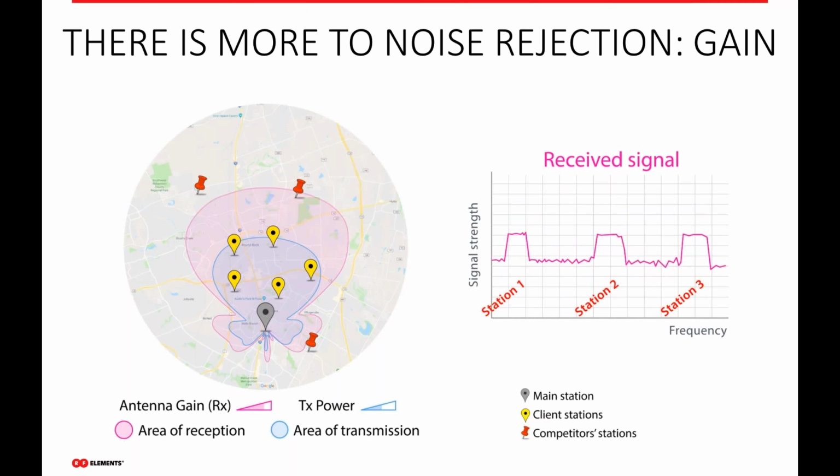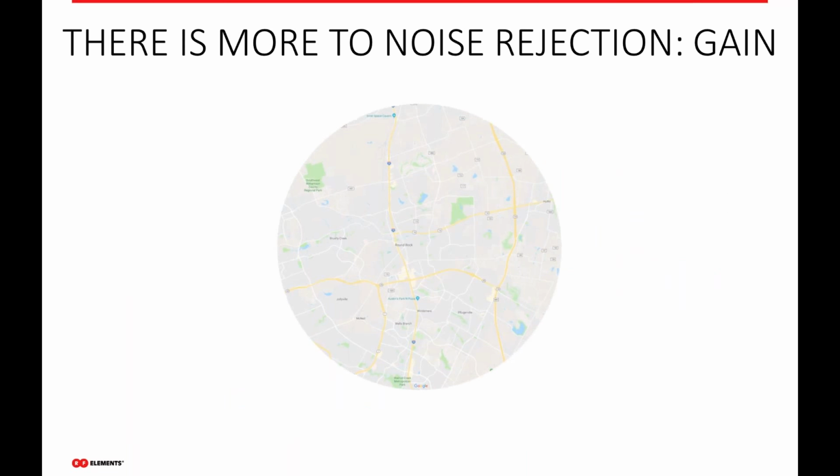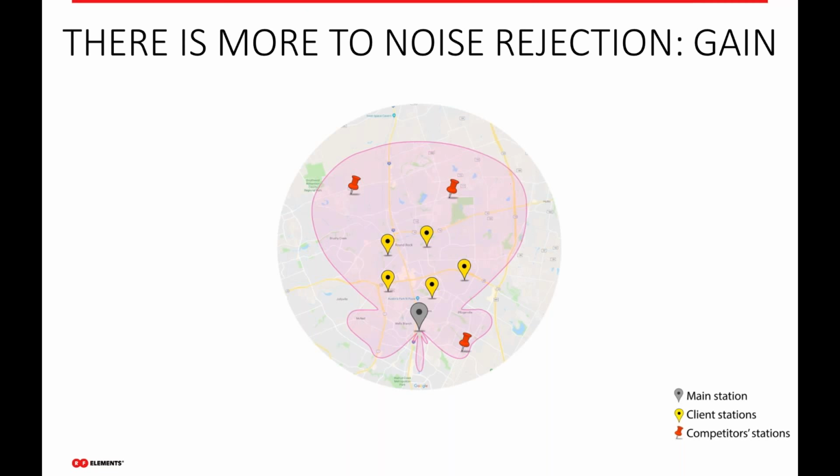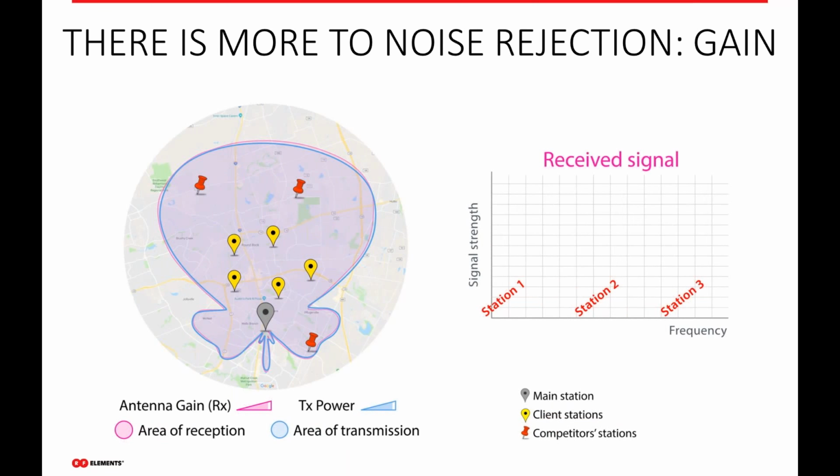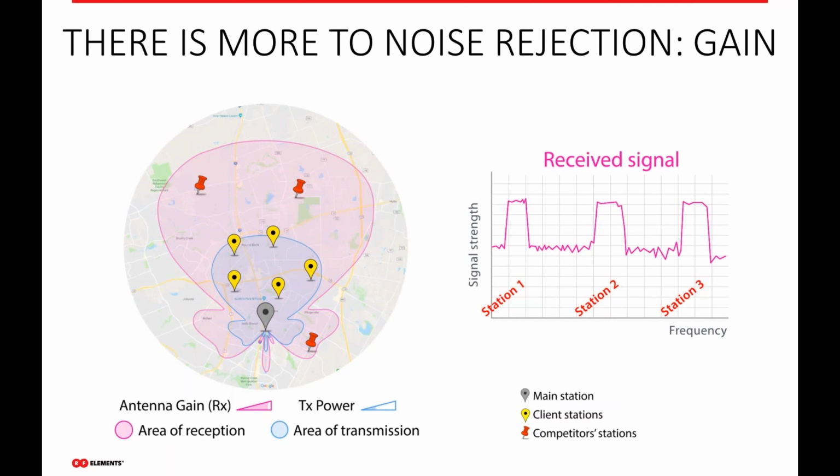But receive gain is fixed. It's the receive sensitivity of your radio on top of the fixed gain of your sector. So this is something that really can't be tuned down or adjusted in the radio like you normally do for your coverage area and your TX power. So when you have areas where the coverage isn't going out very far, why use really high gain traditional sectors?